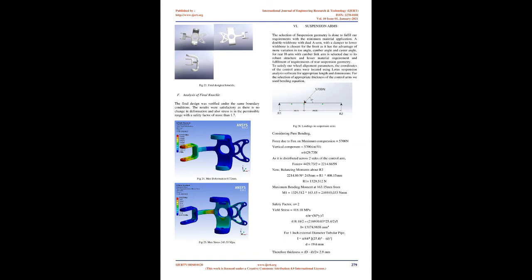In this segment we will be discussing the analysis of the knuckle only. The purpose of the analysis is to make sure the designed knuckle withstands the calculated forces with an appreciable factor of safety. Since the knuckle is a three-dimensional object, we need to have 3D mesh elements inside the volume, and therefore we have used three-dimensional hex-dominant mesh elements of second order with a mesh size of 2 mm and with free face mesh type being quad/tri.